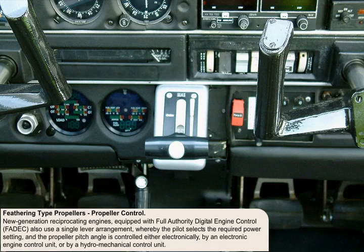New generation reciprocating engines equipped with Full Authority Digital Engine Control, or FADEC, also use a single lever arrangement, whereby the pilot selects the required power setting and the propeller pitch angle is controlled either electronically by an electronic engine control unit or by a hydromechanical control unit.